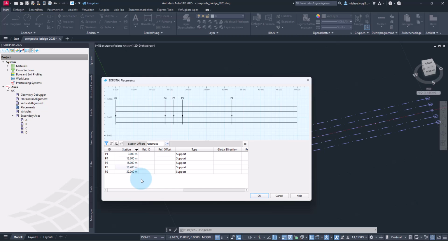To keep this tutorial compact, we will use these positions also as the border between the concreting segments in the span and the concreting segments at the inner support, and we place here also the change from the span cross-section to the cross-section at the support, which has a higher amount of reinforcement.